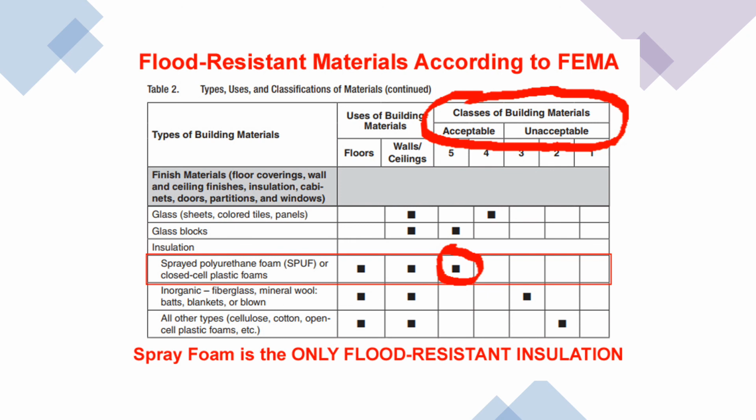There are a lot of different types of flood-resistant materials. They're good and they sound good. We've got waterproof flooring in this building. It can't get hurt. Well, the flooring may not get hurt. But if you get water trapped between the waterproof flooring and the plywood below it, you've still got the same moisture problem, if not worse, than you would have if carpet were on it.